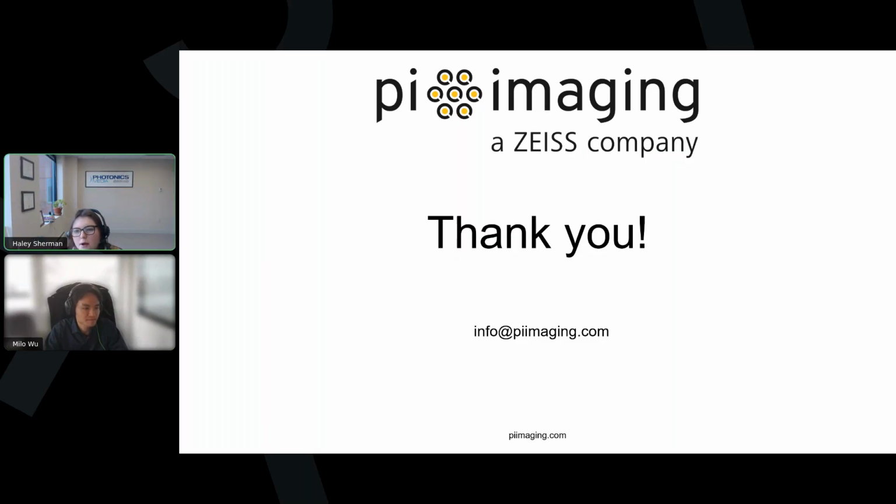Okay. What is the ratio of active to dead area for one pixel? Active to dead area. So all our products have a microlens option. With the microlens, you can typically reach 80-90% fill factor. Without that, it's probably in the 15 to 20% range. But we also develop microlens, so this is typically in the 80 to 90%.